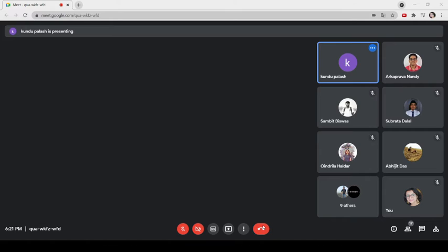Yes, it is the bit format of the TCON register. So there are two registers: one is TMOD and another is TCON. The TMOD register will set the functionality of the different modes under timer, and the TCON register will set the different functions of each timer. These bits are reserved for timer 0: TR0, the timer control bit for timer 0, as well as IE0, which has a separate functionality, and IT0. Similarly, that is 3 bits.